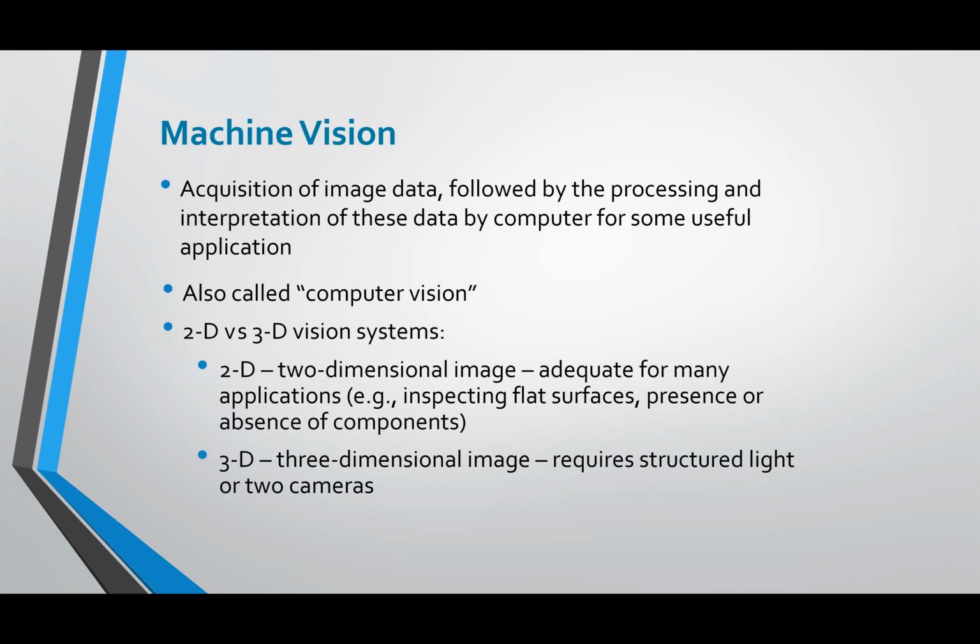For machine vision, we're looking at acquiring images, and that computer vision system can be done both for 2D and 3D applications. And again, using those cameras, light, laser, comparing to what the desired quantity would be, you're able to use vision systems to inspect 100% inline inspection. And again, this could be presence or absence of a label. This could count the quantity of a given item. It could inspect for different levels, fill rates,